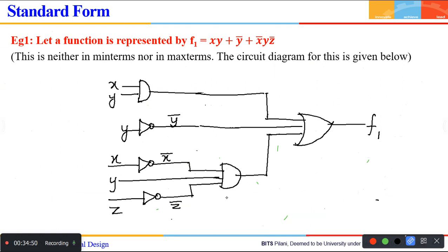So what do you have to do at that time? First you have to simplify this. You can draw the corresponding logic diagram using basic gates, which is very easy. After that, replace every gate by its equivalent universal gates. Once you do that, look for redundant gates and remove them. Do all these operations in pencil, because if you draw in pen you will not be able to remove the redundant gates. Then you get the final logic diagram. Have you understood this? Okay?